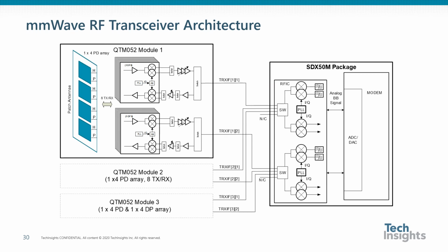This completes the picture. The antenna module combines the signals from the antenna and converts them to IF. The IF is routed to the RF-IF chip within the modem package, where the IF from the individual modules are combined and then converted to baseband. The baseband is then converted to and from digital within the modem die itself.